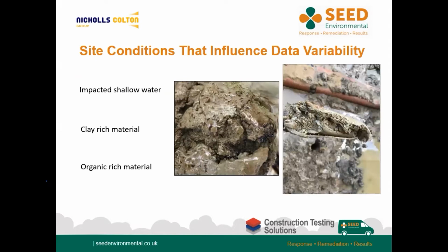Once soil samples have been retrieved from site and you are completing your on-site headspace VOC assessment as outlined earlier, and you're logging sample descriptions, it's important to note if your samples have been collected from above or below the water table. If your unsaturated arisings are clear of visual and olfactory evidence of contamination, and the PID is returning negligible concentrations, but your saturated soils at the same sampling location return evidence of contamination, it may be that you are recording a groundwater contamination issue.